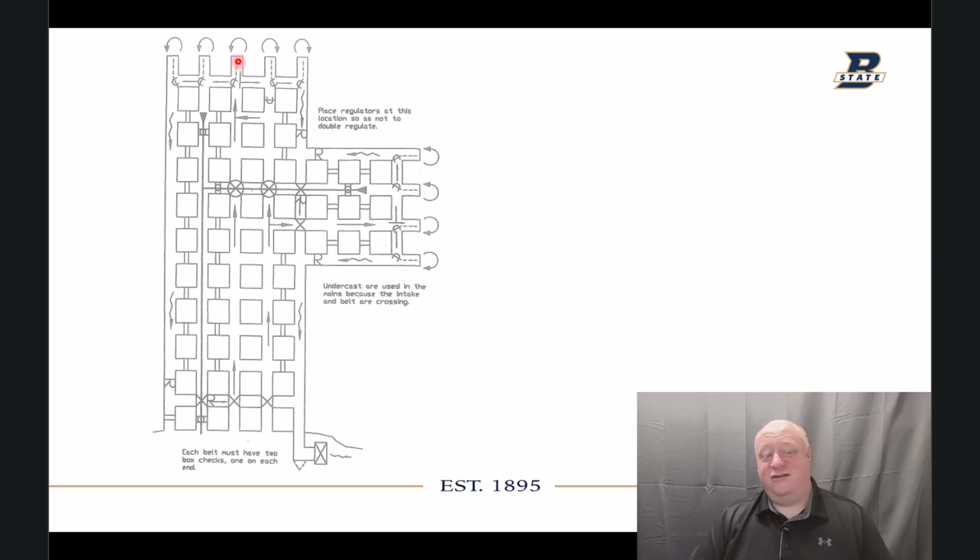But because these aren't driven up out ahead, your haul distances just don't add up, right? So in this case, you'd actually probably want to drive these 3 entries sort of up out ahead of these and get started connecting your ventilation in here as you go, and then you see what I'm saying?